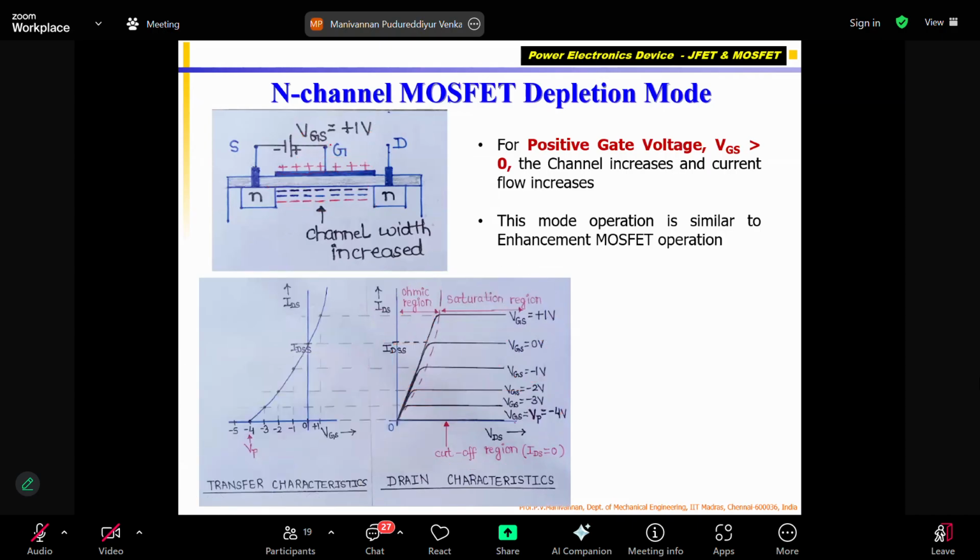I am giving input voltage to the gate, and in between there is an insulator. The resistance of this is 10 power 9 to 10 power 12. Okay, he gave 1 volt. Current, how will it go? From here, it has to go through the insulator and reach the P. In a transistor base, it happens directly. The insulator is not there, so automatically current goes inside because of the low impedance.